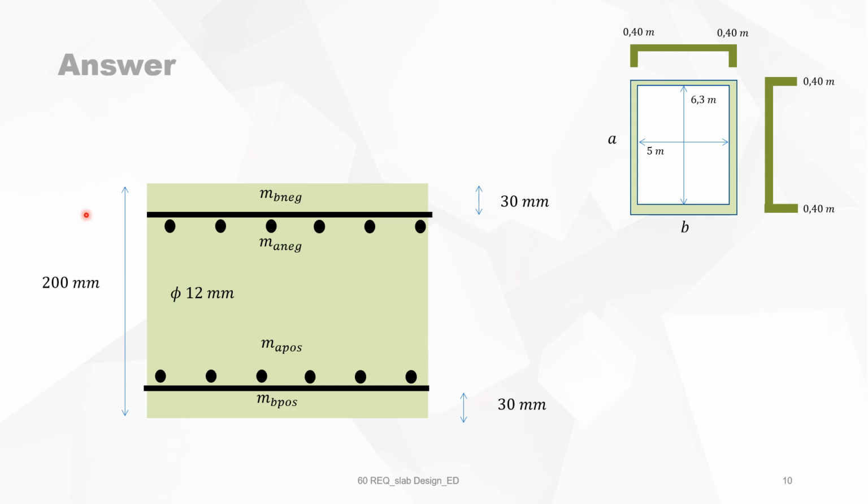So to summarize it now, this was the plan view of the slab. That is where the reinforcement is going when you make a view by cutting it like that. And then you see it's all diameter 12, top reinforcement is 9 per meter, second layer 6 per meter, and the reinforcement for the positive bending moments is 5 per meter, and in second layer 3 per meter.